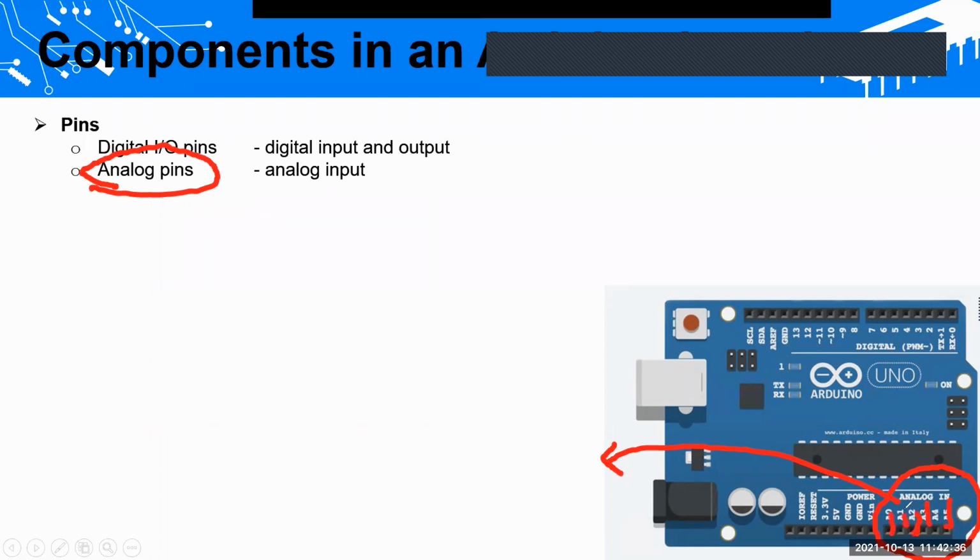So if you need to give certain analog output, you have to use these PWM pins 9, 10, 11 in this Arduino board. If you are considering another Arduino, like the Arduino Mega, it has more PWM pins, and the mapping also differs. Now you have digital pins, then the analog pins. Digital pins you can use for input and output, as well as analog output, so three purposes. If you're using it for analog output, the pins should be 9, 10, 11 on Arduino Uno.